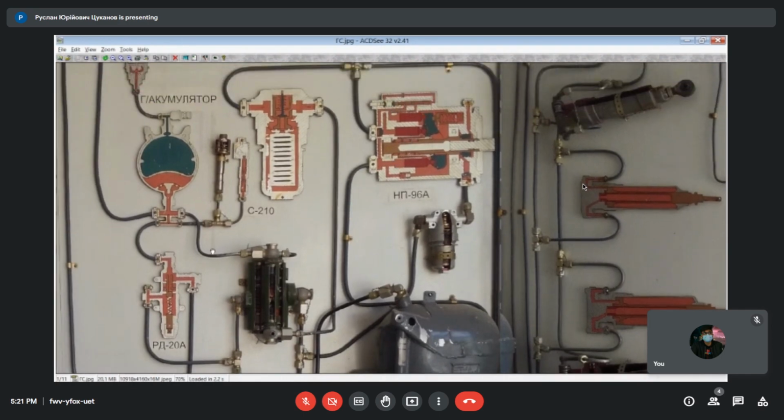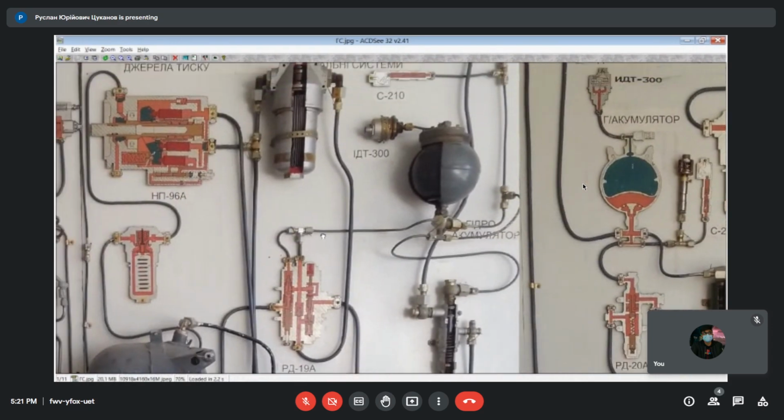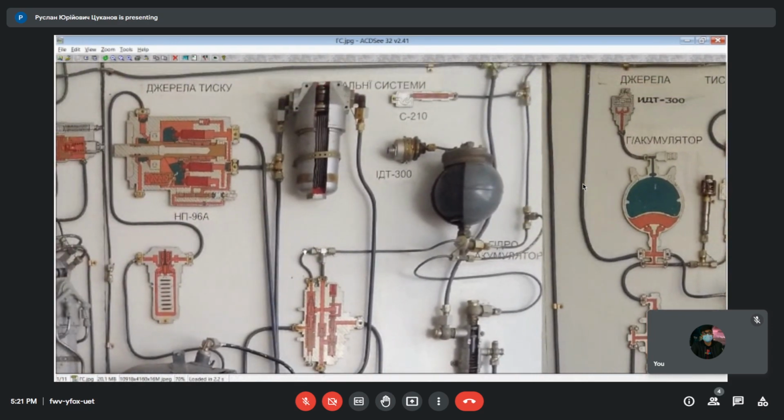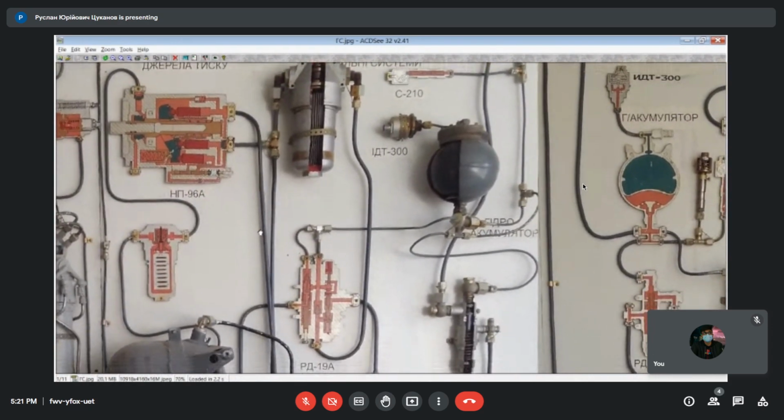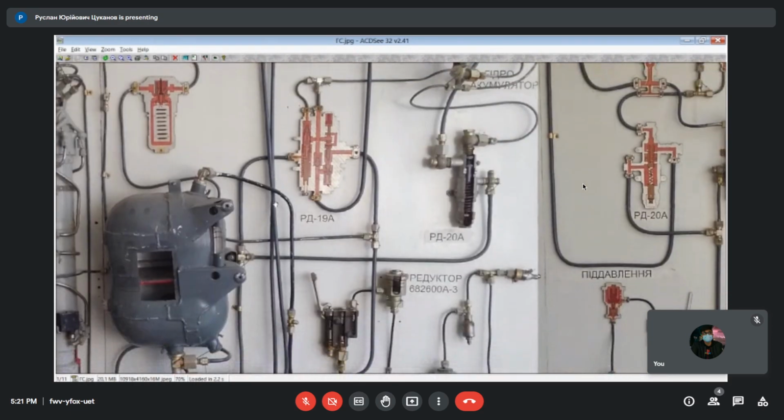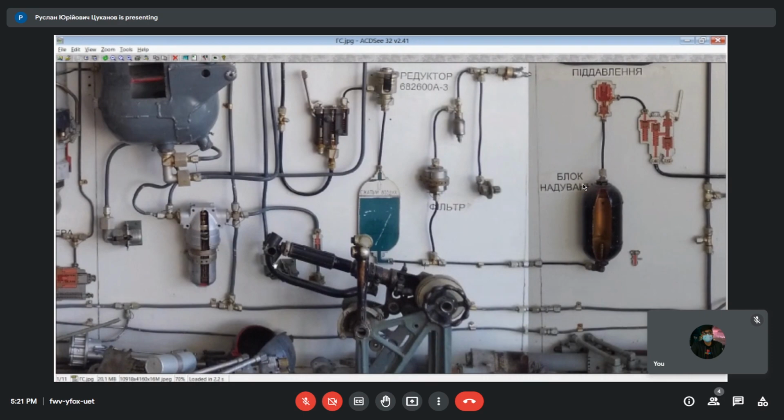Hydraulic pump, here there is only a picture, because if you look at the side view, you will see nothing. From the hydraulic tank, there is an outlet to the pressure line. And here you see a T connection. With the T connection going from another fitting. The ground pump has a suction connection and a pressure connection. These connections are especially made of various sizes.